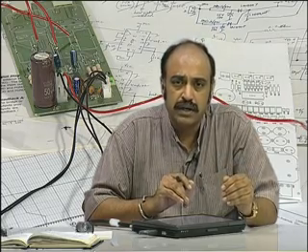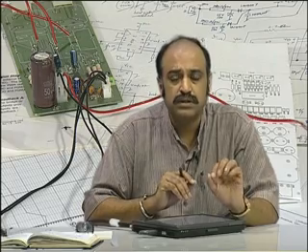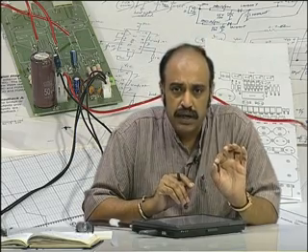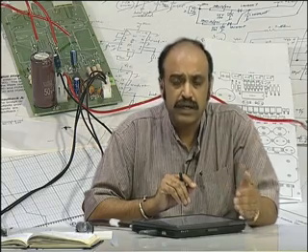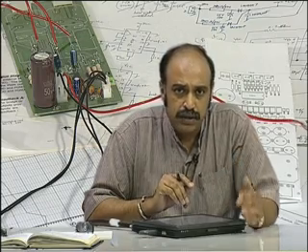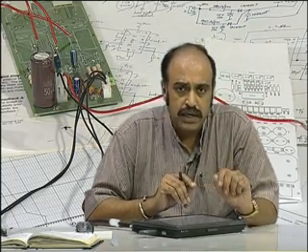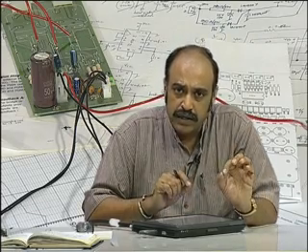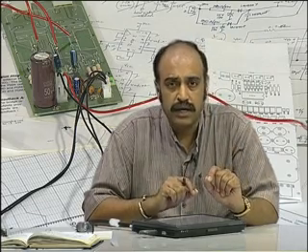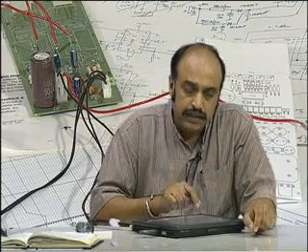When you restrict to electric circuits, if it is an inductor, the inductor current is a state variable, and if it is the capacitance, the voltage across the capacitance is a state variable. So, after having identified all the inductor currents and the state variables, mark them on the circuit.